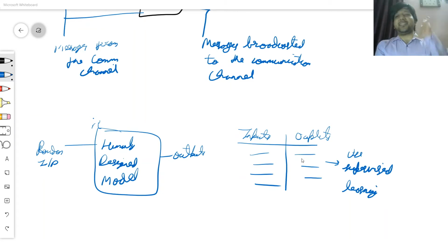So use social potential field for the obstacle avoidance behavior and for the goal-seeking behavior. Generate a data set, so you don't need to do anything. You just need to write a computer program that generates a random map, puts a robot randomly in that map, and then lets the potential field work for whatever time possible. Once the robot reaches the goal, you put it on another random location and let it reach. Once you're bored of it, load the third map, the fourth map, the fifth map. You've got too many maps.